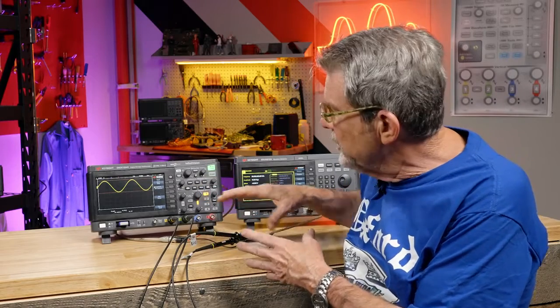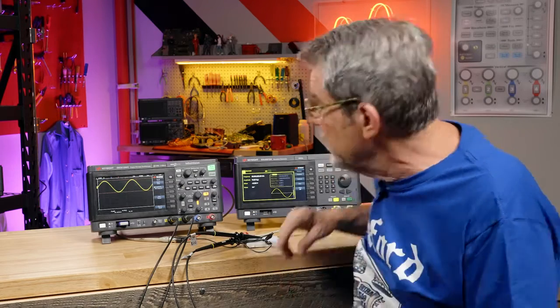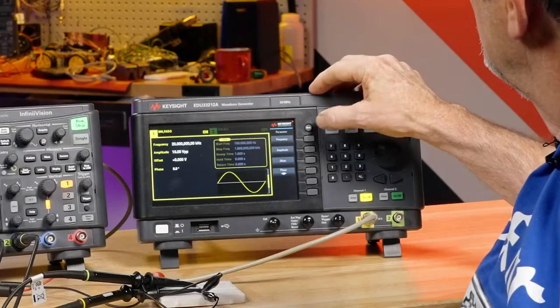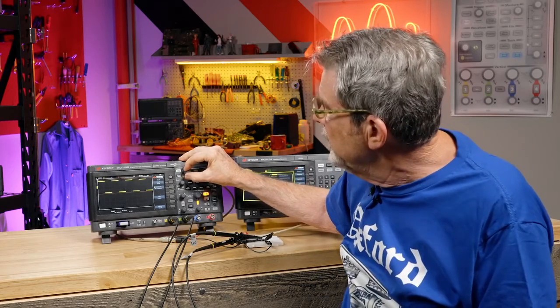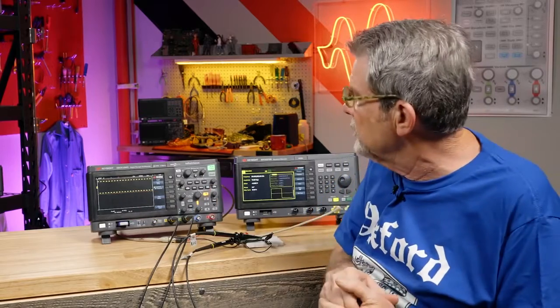Let's now convert a repetitive clock signal or square wave from the time domain to the frequency domain using the FFT math function. So here's our VN on our resistance divider network, our 10 volt peak to peak. I'm going to change this to a square wave, or you might call it a clock signal. And we're going to do an FFT, Fast Fourier Transform, on this, but my first recommendation is to get more cycles on screen. You can get better resolution for the FFT if you have more cycles.